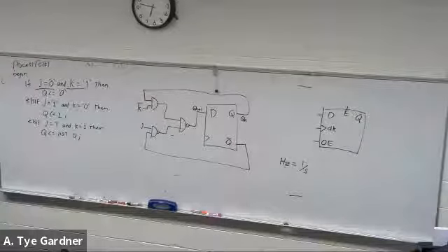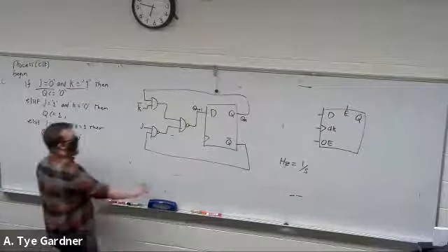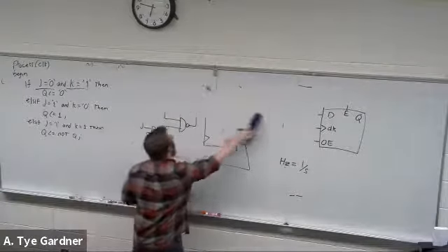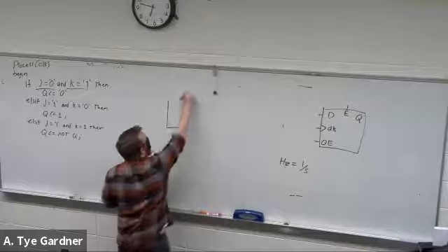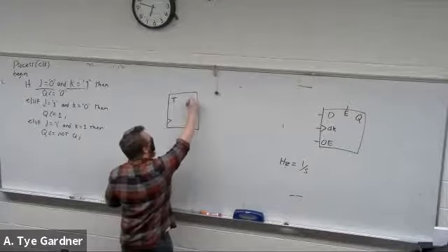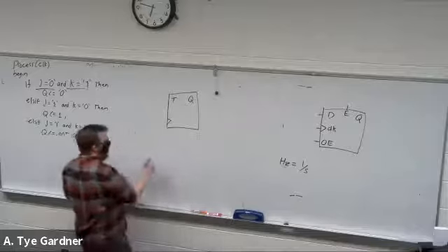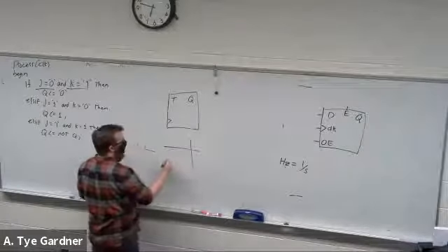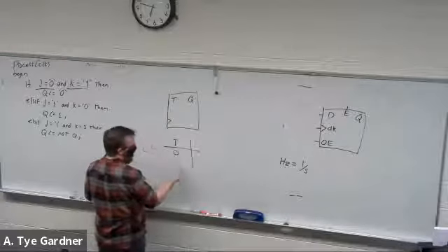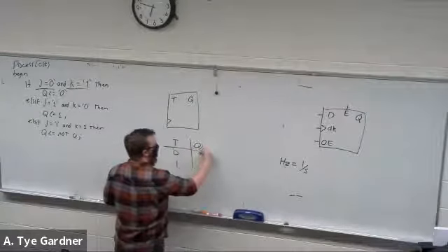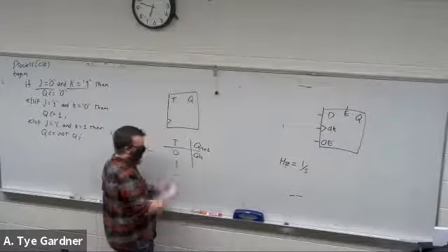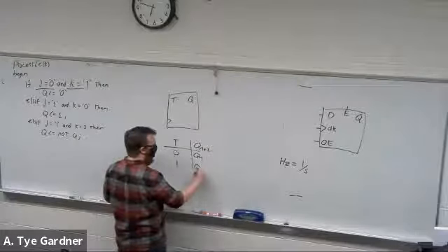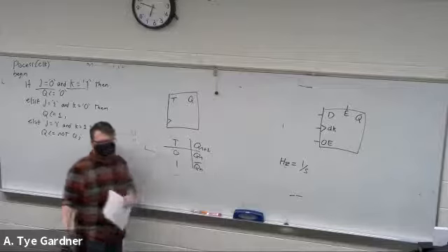All right. The next one is the simplest one of them all. They're kind of cool. They have some really interesting applications in clock division, especially. They're just called T flip-flops. And their truth table is the simplest of all, where T is either 0 or 1, and Qn plus 1, if it's 0, is Qn, and if it's 1, is not Qn.